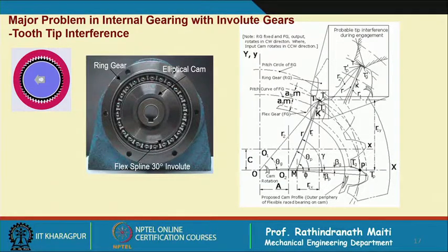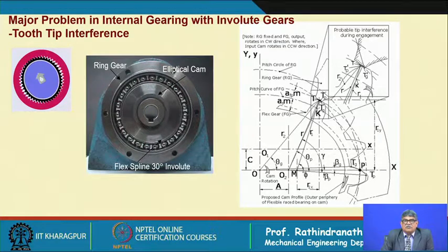Now, in designing this gear unit, there are many problems. First of all, as the teeth are not involute, standard gears cannot be used directly. So, we should find some other teeth which are involute-like. Usually it is possible to find a pair of conjugate tooth profiles having this motion. It is not possible that conjugacy can be maintained 100%, but still it will be better than involute teeth. So, finding such a tooth profile is a major work in designing such a gear unit.